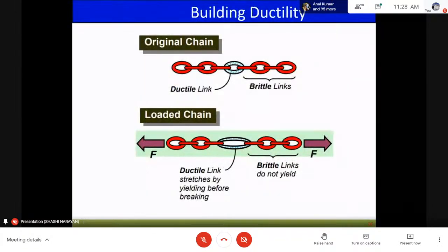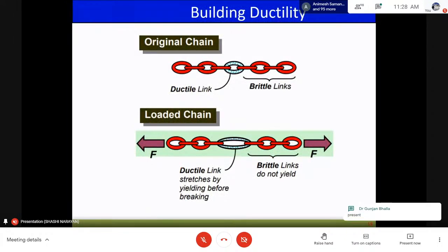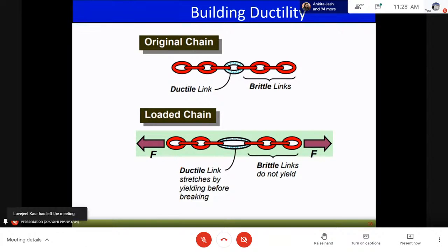So this R takes into account the ductility requirement, in the sense that if the structure is more ductile, we can have a larger value of R. For the moment resisting frame with ductile detailing, we take a value of R as 5. If it is brittle, like shear frames, we take a lower reduction factor, because there we have a brittle failure rather than a ductile failure. So, what is actually ductility?